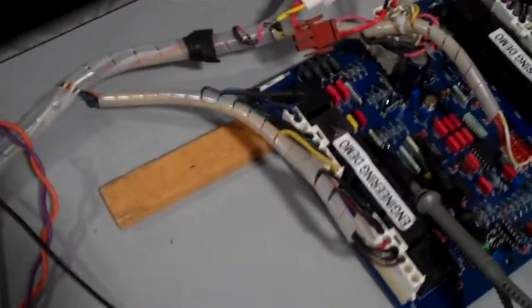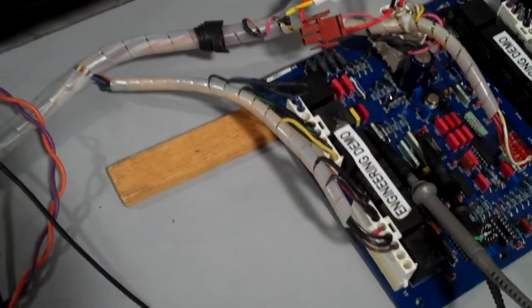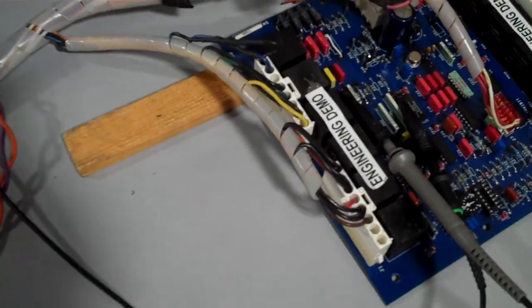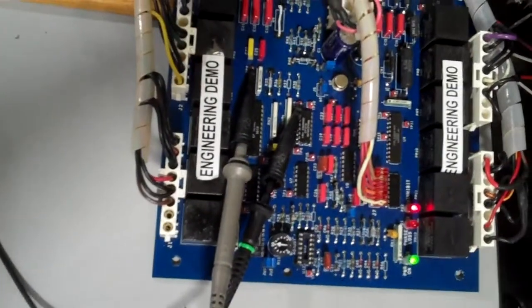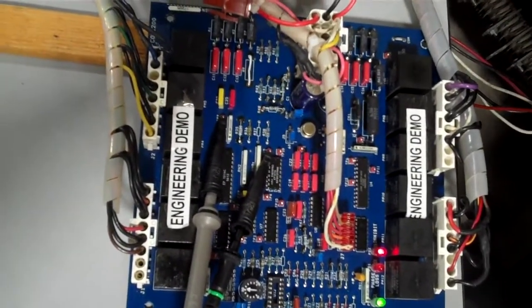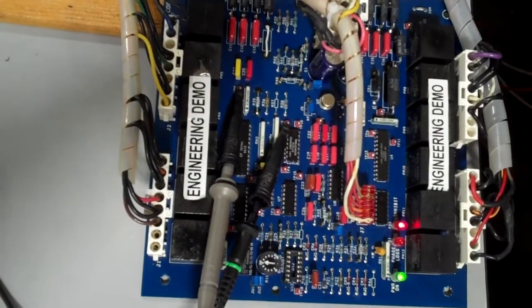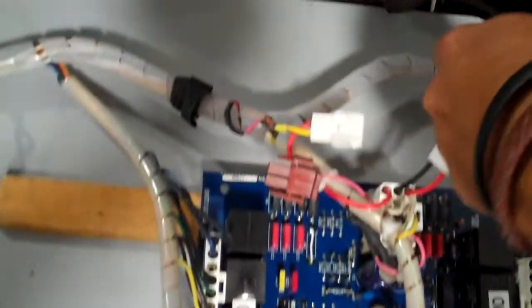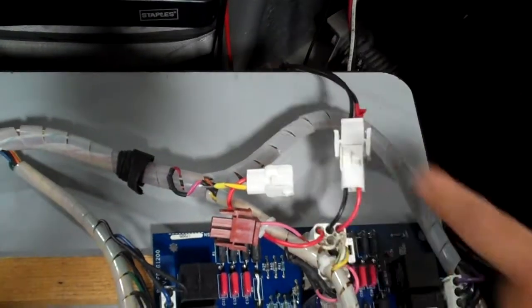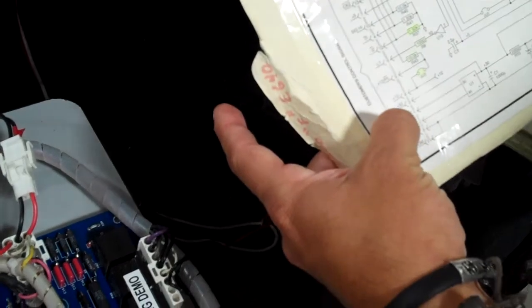Alright, today is July 31st, 2018, and what we're going to show here is basic working parameters for an FCOG1200 board at low power. What we're going to do first is power the board with 24 volts AC on positions 1 and 2 of J6.